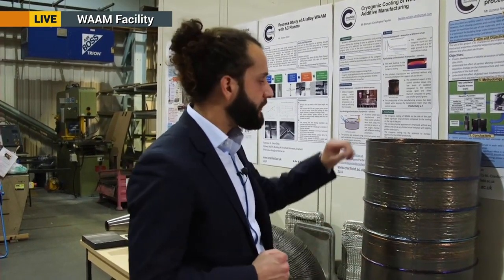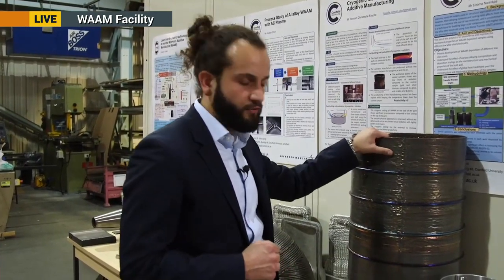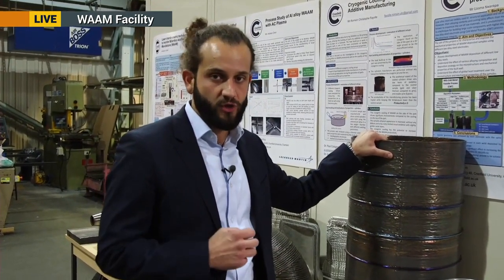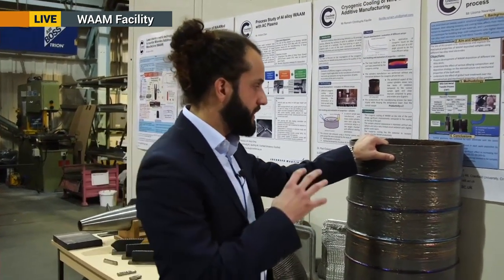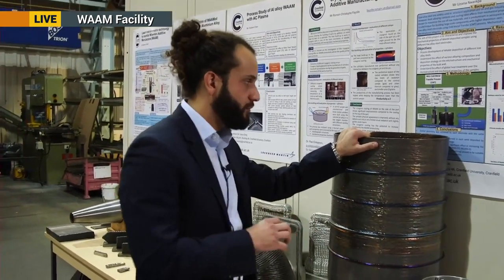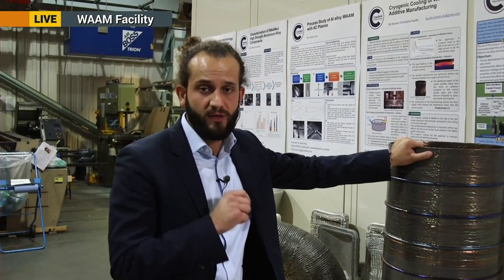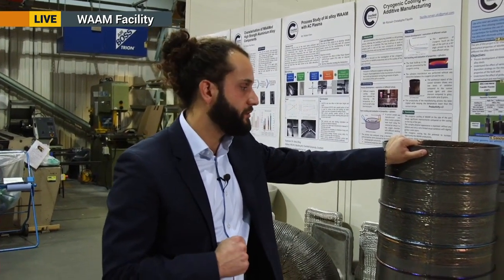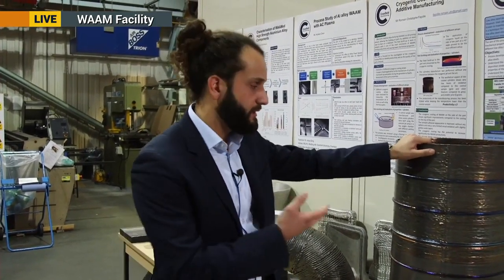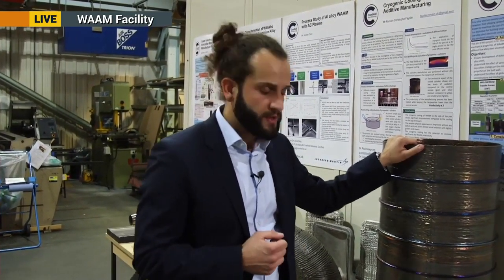So instead of having 3 separated components and the associated supply chain, now we can do everything in one go. Then we go from the preform made by WAAM to the finished machine component, and by doing so we can reduce the amount of titanium which is wasted by over 200 kilograms for every tank that we made. The tank also happens to be 60% cheaper to make, and it could be made really in a number of hours as opposed to several months.